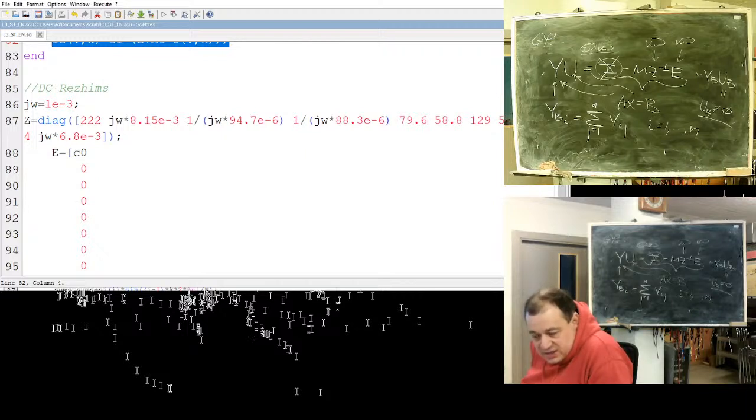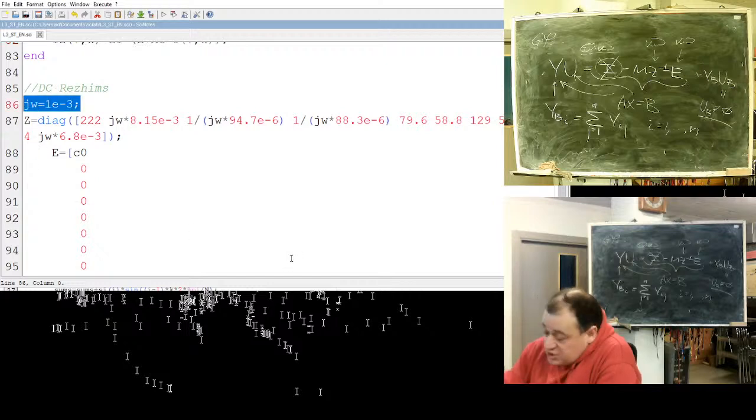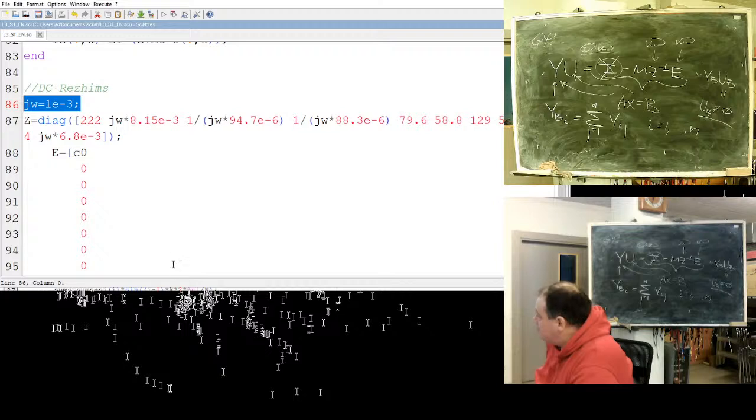If the coil has a counted active resistance, it will remain, but the inductive part should disappear. This means what I need: separate schematics for the DC regime, with a separate nodal matrix, it's all separate. Again, I'm lazy. What have I done? I'm calculating the DC regime as an AC regime at a frequency of 1 milliradian per second. It's a very slow AC regime. Some 20 milliradians don't change anything. So it's all zeros? Near zeros.